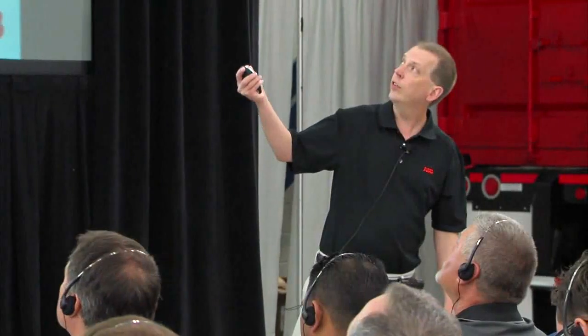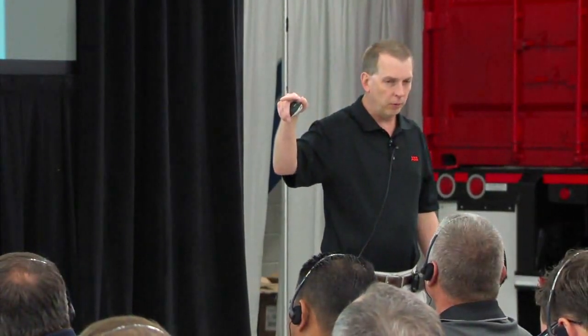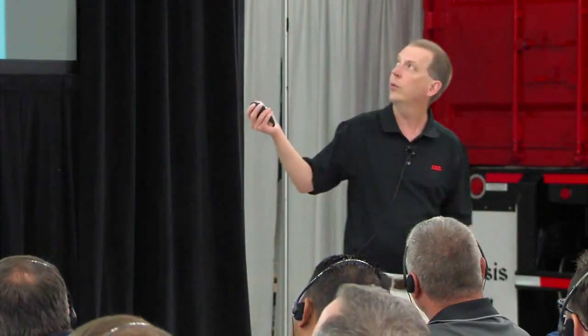So if we know we're going to have that kind of situation, we tell the drive to use a flying start mode. It sends a small amount of electrical current out to the motor, and it watches the current coming back on those current detectors, and it estimates where the motor is based on its current signature. It's searching for that speed. Say it's going half speed: it'll start at full speed and ramp down until it finds it. Once it finds it, it'll accelerate back up to speed. So it's a way to catch a flying load. If you've ever heard of flying start or catch on the fly, that's what that term means: to catch a rotating motor.